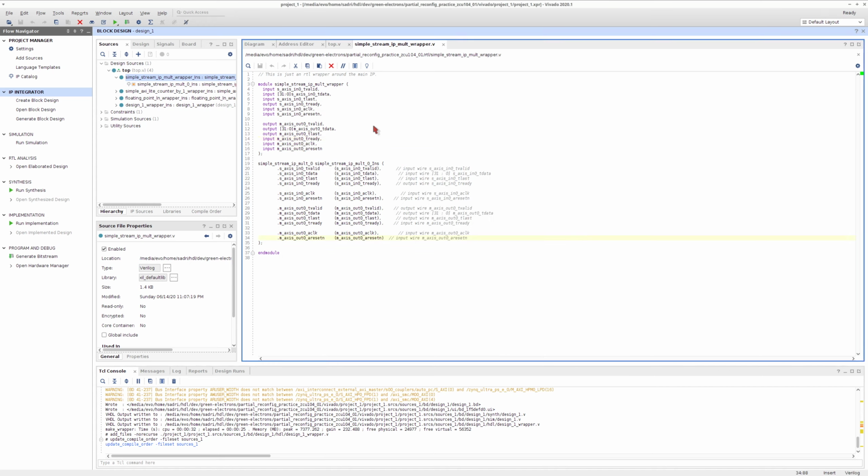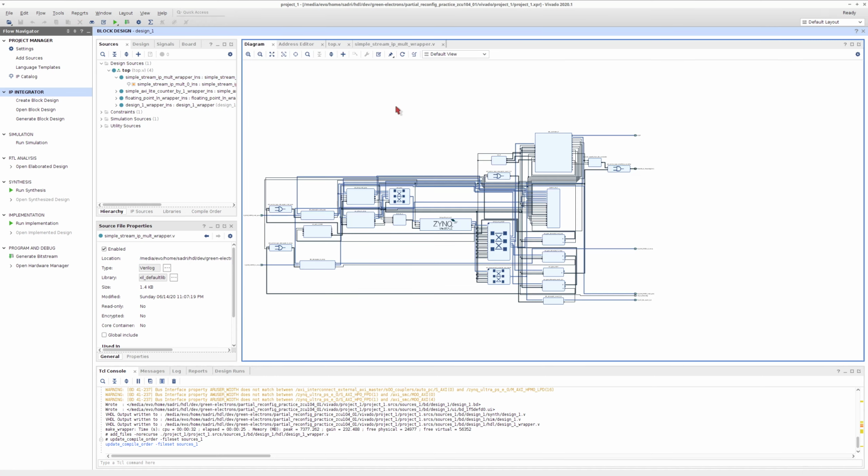Okay, so I believe that the Vivado design is to a good level studied, and I hope you have understood whatever I have done here. I think all of the points are mentioned, and now for this design, a very important next step is you run the synthesis, or you can also open the elaborated design. You can run the synthesis, open the synthesized design, or you can open the elaborated design. And very important is we need to do a floor planning for our design. Basically, for each of my 3 reconfigurable regions, I need to tell the tool where these regions should be located on my FPGA. This is the very important next step.